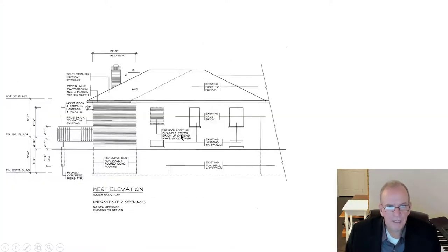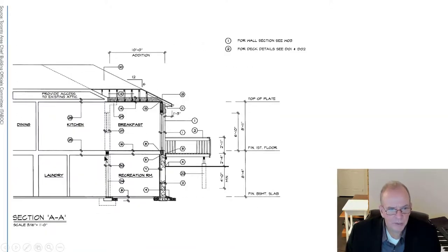Like for me, looking at this section quickly, I noticed this. So in the basement, do I want to have that little bump there? I could obviously put an outside corner on the drywall. I could do that. I would be looking at the ceiling height. I would be discussing that with the client because I could easily make that flush going across here. So I could make that flush. I could either use a heavier joist, so there'd be less spring in the floor, or strap it down.